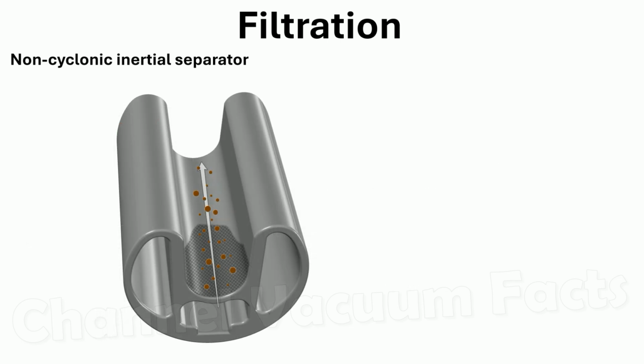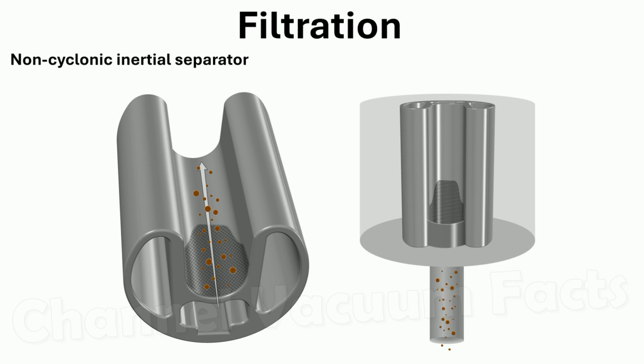Large particles can't get through the mesh and have too much inertia to get stuck on it, and the inrush air continuously aerodynamically washes it. Instead, it gets flung out into the bin by the U-shape. This mesh therefore doesn't clog as easily, even upside down, and the pores can be reduced to as small as 100 micrometers, making it separate dirt even more effectively.